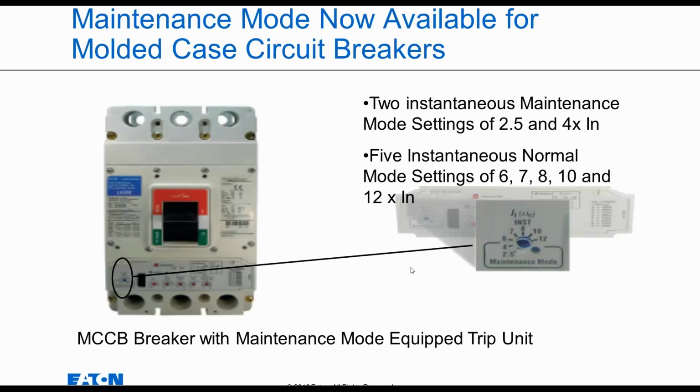And here's another slide just to show you that maintenance modes now, even in molded case breakers. Because of the National Electric Code, we didn't think we needed it in smaller breakers. Many customers now are asking for it in smaller and smaller amperage breakers, no matter what level, even below the NEC level that it's required in.